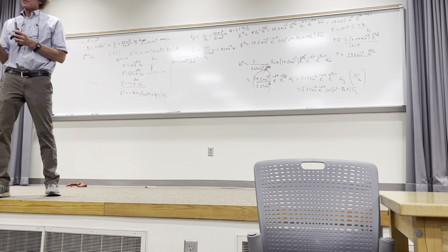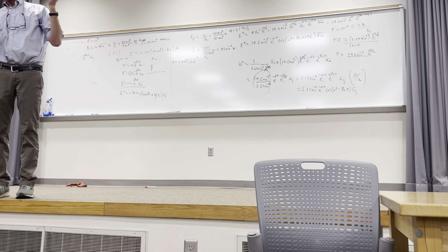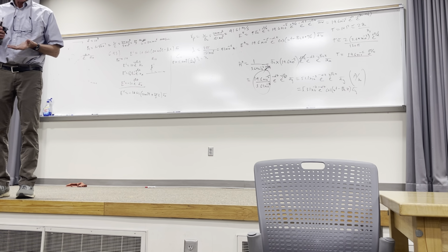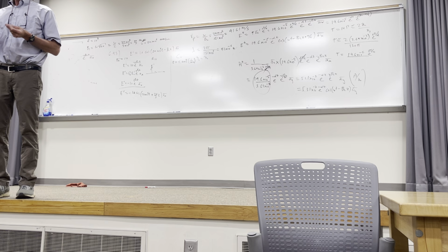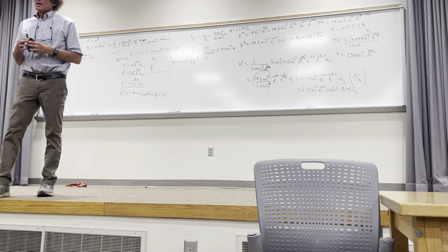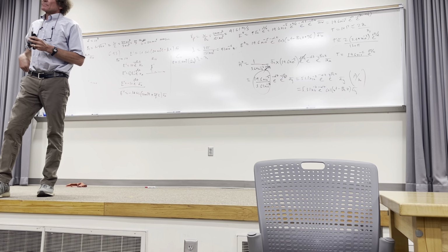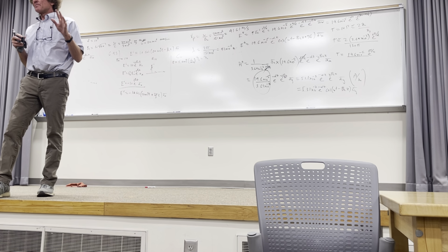Then we've moved into magnetics, and we've done everything with magnetostatics. We talked about Ampere's law, how to get the H field from symmetric current distributions. We talked about the boundary conditions too. E tangential 1 is E tangential 2, H tangential 1 is H tangential 2 if there are no surface currents. We talked about inductance, how you get inductance based on either internal inductance or external in some cases, but we've talked about those.